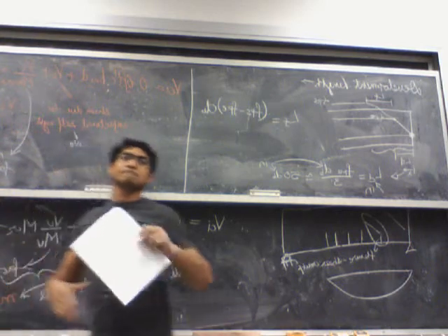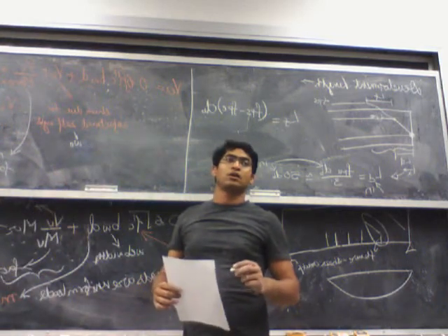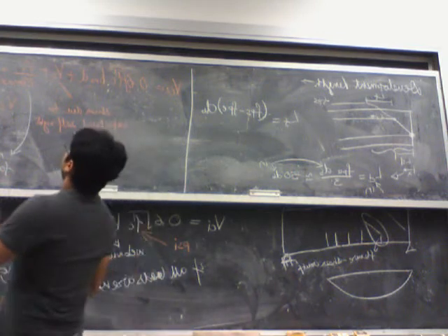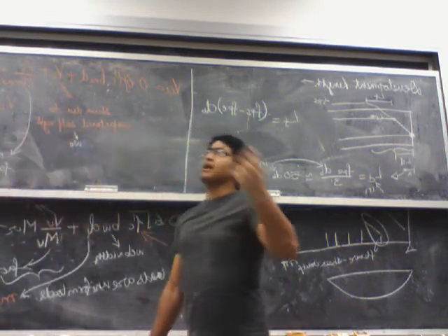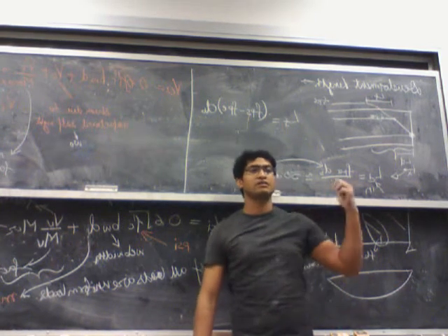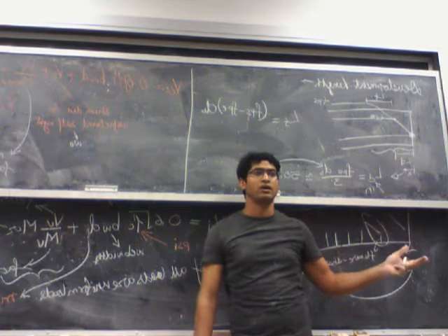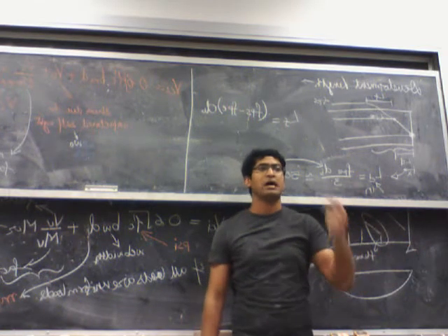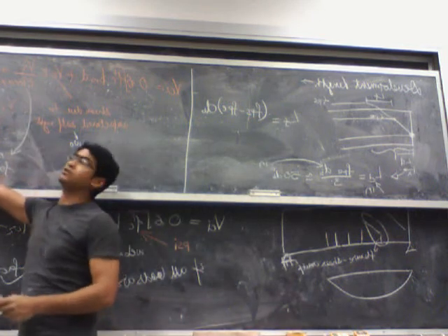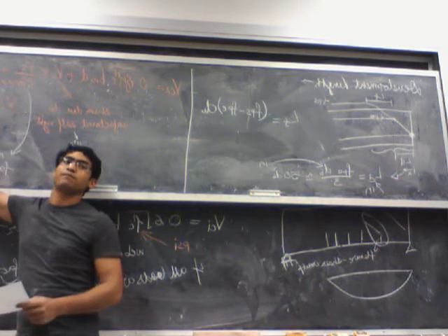Is that M max the same thing as M? Actually, no. It is delta M, but with the factored loads, because the M max that we use in the feasible domain or the limit zone is with the unfactored loads. Oh, okay. But in this case, it's the factored loads except the self weight. Okay.